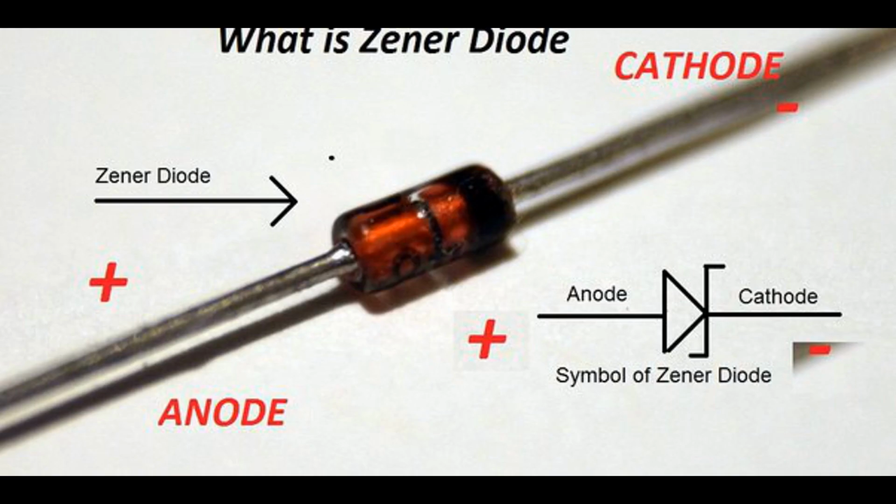There are various methods and instruments used for voltage measurement, depending on the level of accuracy and the specific application. Some common methods and instruments include multimeters. Multimeters are versatile handheld instruments used for measuring various electrical quantities, including voltage. They come in analog and digital versions and can measure both AC, alternating current, and DC, direct current, voltages. Multimeters often have different voltage ranges, allowing measurements from millivolts to kilovolts.